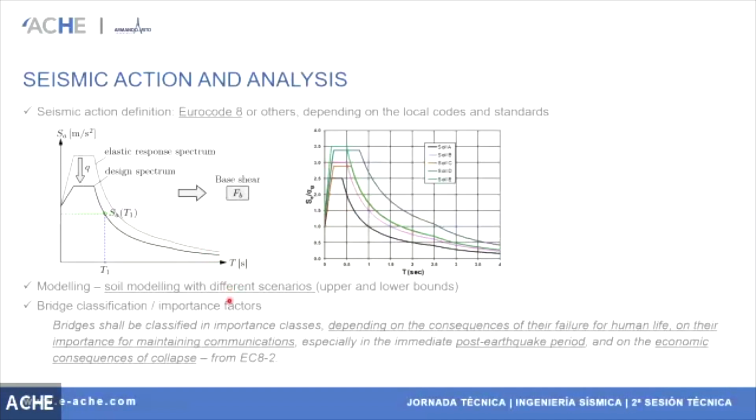Soil modeling with different scenarios. Yes, sometimes, mostly when you have deep foundations, we have to consider different scenarios, with liquefaction and without liquefaction, and consider some differences in, for example, the springs that you put to simulate the soil on your piles, and then you have to consider some lower and upper bounds to design your bridges.